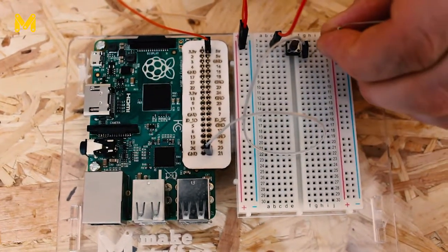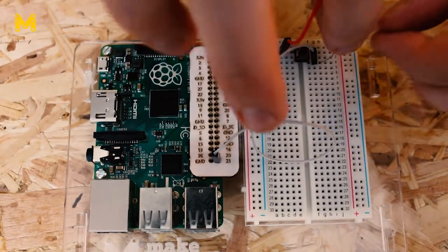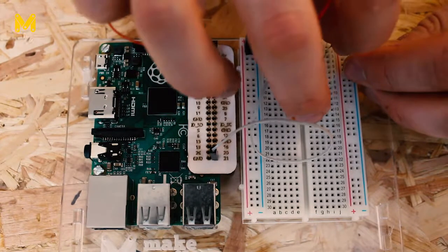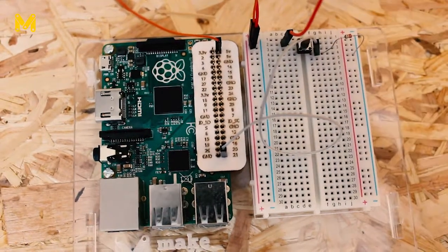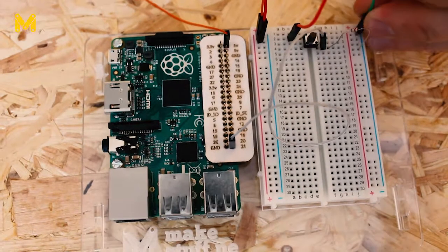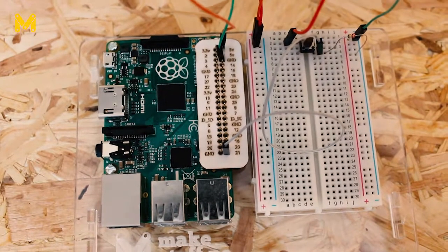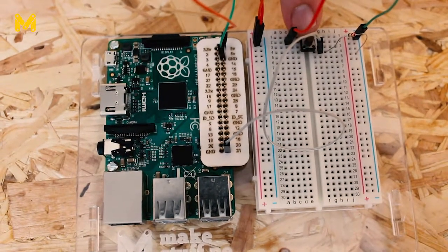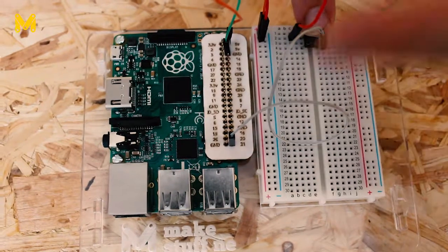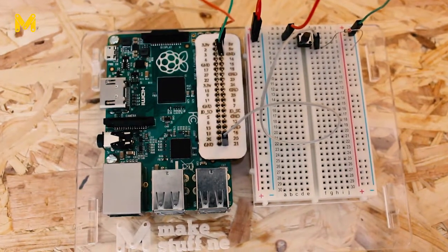Now, the next thing I'm going to do is take my resistor, and I'm going to take it from this bottom leg over to the ground rail. Just like that. And I'm going to complete my circuit by going from the ground rail over to the ground pin on my Raspberry Pi. So the electrons are currently stuck here. When I press the switch, they will flow into 21, and we've got a circuit. Now, if our circuit is built correctly, we can use this analog input to control digital programs on the computer. That would be pretty cool.